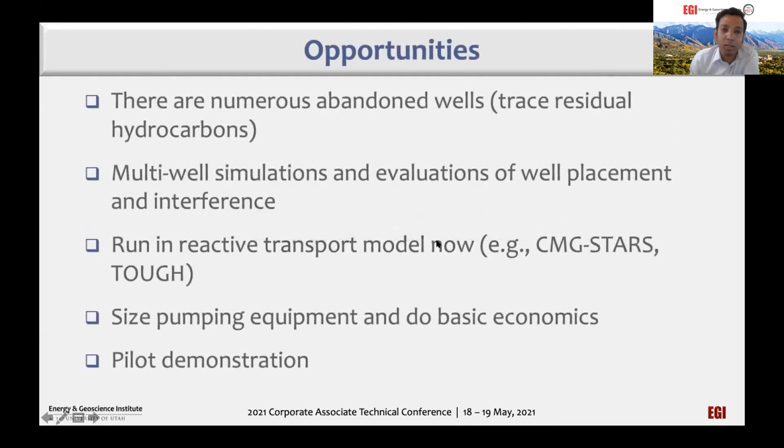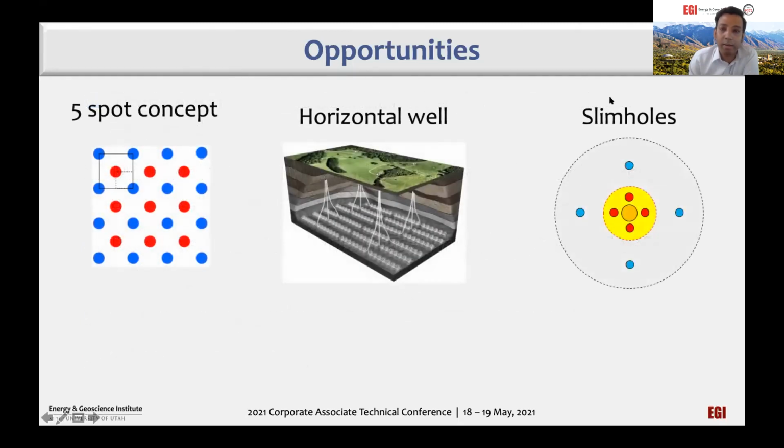But we have a lot of opportunities. There are numerous abandoned wells, but the problem is that we may have some trace residual hydrocarbons. We need to study multi-well simulations, or we need to study the well placement and interference. In these preliminary studies, we did not consider reaction. We may need some advanced simulator like TAF or CMG STARS. We need some basic economics, and need pilot demonstration. There are three other concepts other than the two-well concept, like the 5-spot concept, horizontal well concept, and slim hole concept.